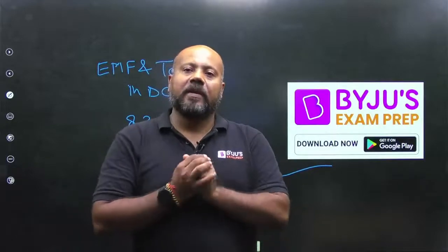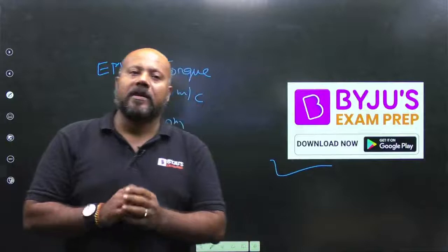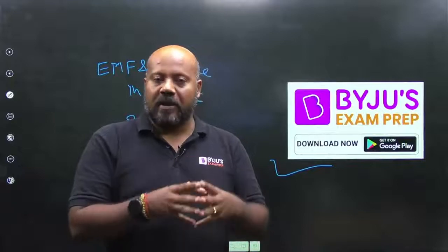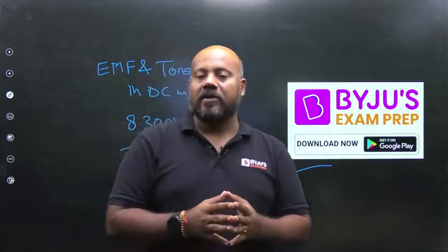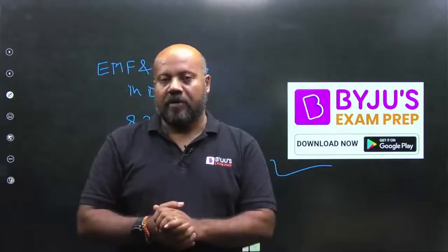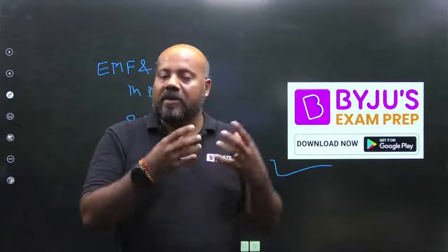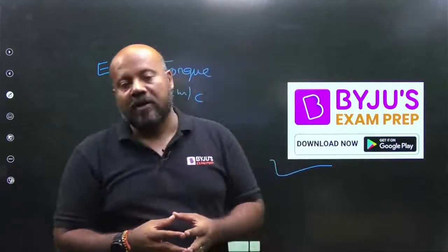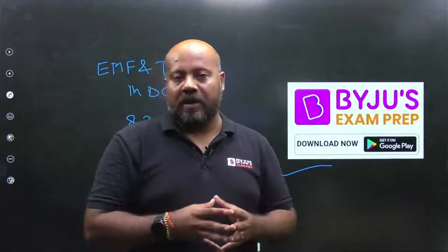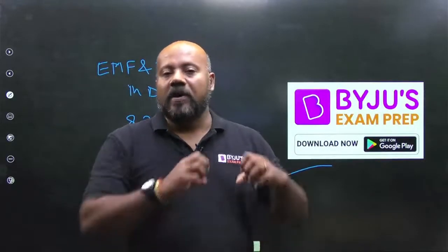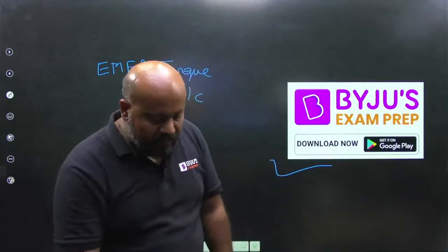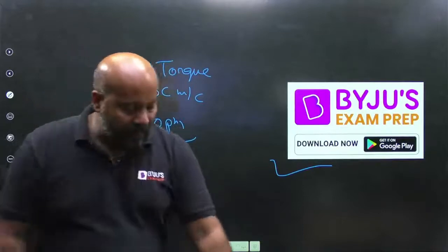Mr. Prasanna Kumar is asking, what is the main difference between compensating winding and interpole winding? See, the only difference is their objective. Compensating winding compensates the cross magnetizing ampere turns of the armature winding under the polar region, whereas interpoles are in between the main field poles. So interpole winding compensates the cross magnetizing effect of armature reaction in the interpolar region. The basic purpose of having compensating winding and interpole winding is to remove the problem of commutation. Armature reaction and commutation. Is it clear?